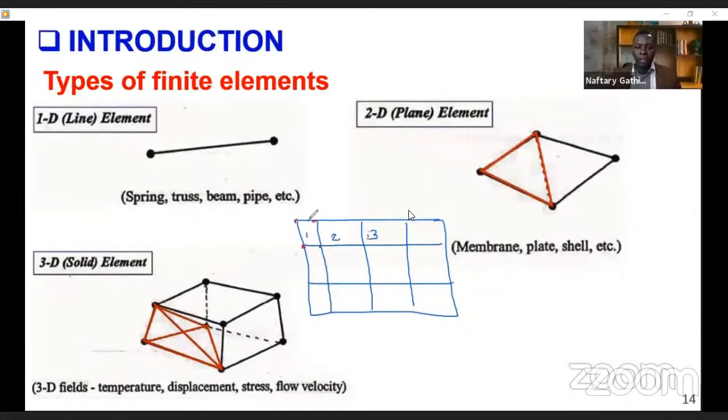Now we extract this individual element. This is the one that we have given here in this figure. In each of the nodes, remember we have ignored the thickness direction, we assume it's negligible. So we have the axes Y and X direction. For the nodes I, J, K, L, we have the coordinates X_i, Y_i on each node, this is X_j, Y_j, like that.